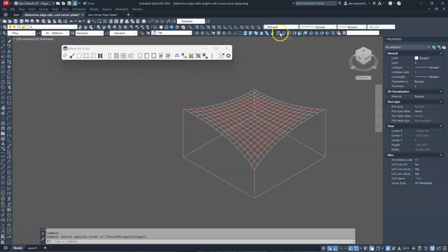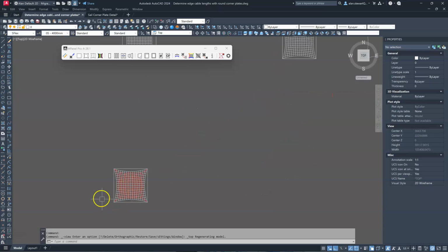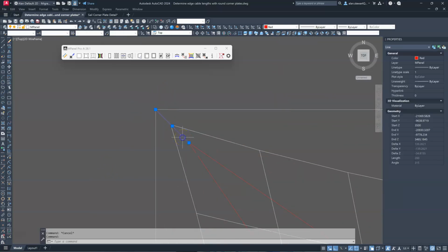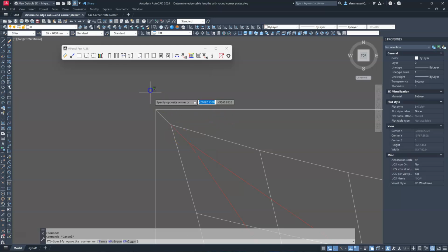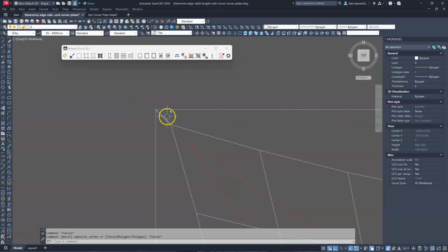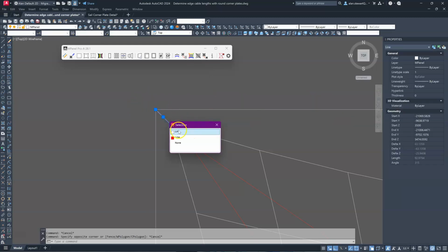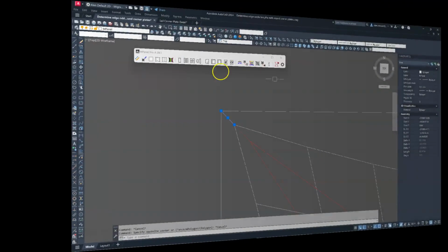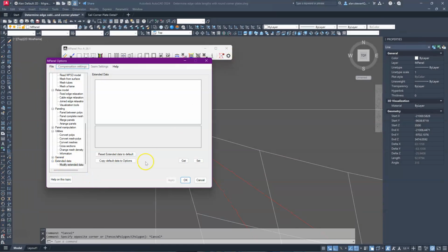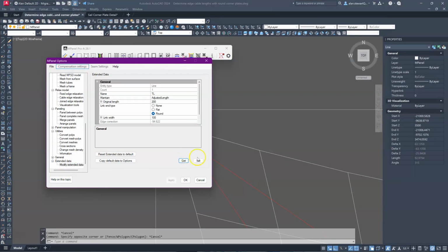Now when we go to plan view, we'll see that the link length, this is the original length here, and this is the new adjusted link length. Now we can look at the properties for this link length. I'll select it individually. We can see it's 93 in round figures long. Alternatively, we can right click on the gear icon here, get the extended data for this link.